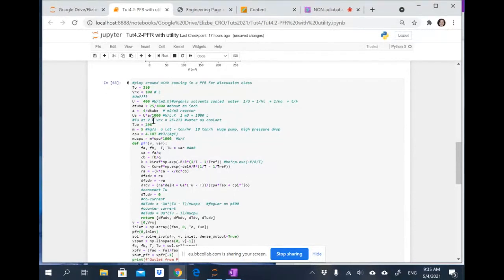But it takes work to get a utility at 310 Kelvin. I'm now going to have to blend it with something else. So I can't just get it from our cooling tower where the cooling water is produced. Water is being cooled to be at a specific temperature. I'm going to have to blend it with something, and then I know you all hate CPB for now, but then I'm going to have to build in a control loop in order to have my utility temperature at a higher temperature.